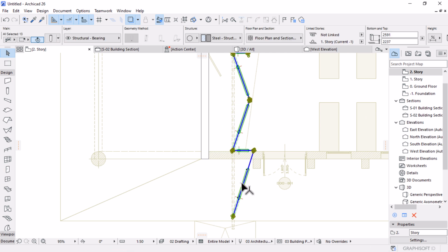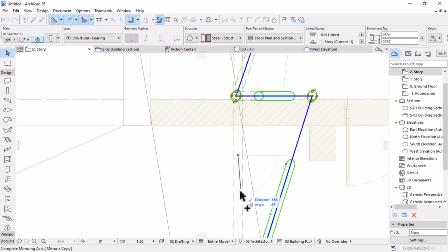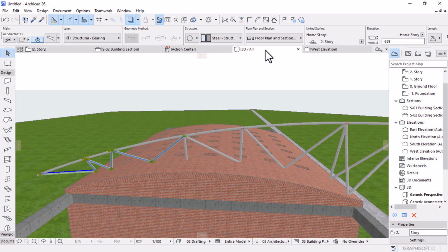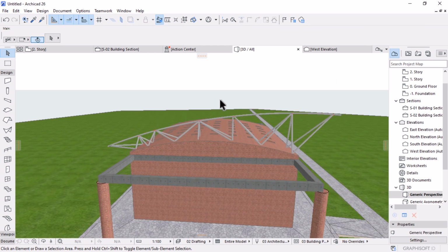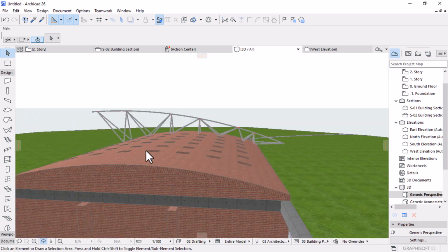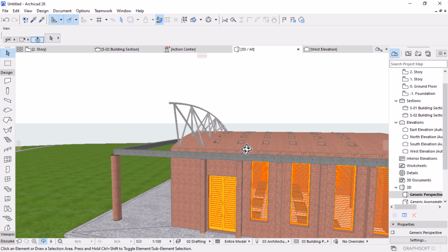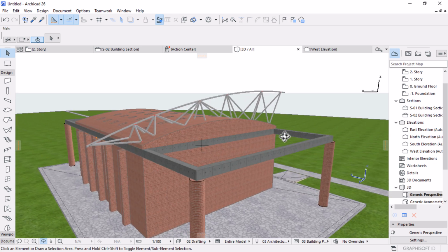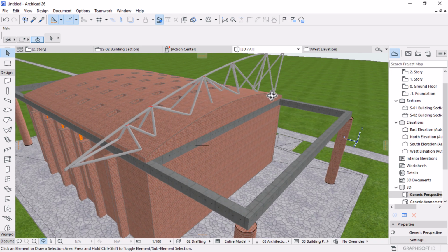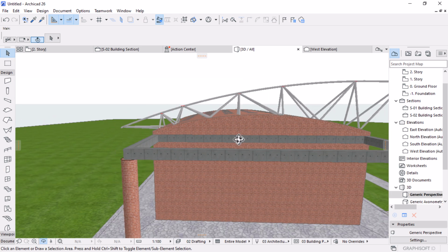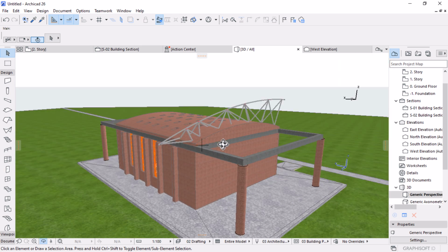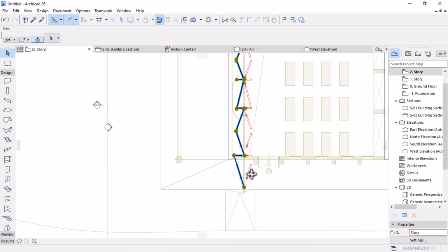Okay, so Control Shift M, use the midpoint of your beam so that you can have something like that. If you check on 3D, that's basically what you have. That's your truss. Obviously here is going to be a different truss, guys, because we don't have this splay or this bend, so it's going to be straight, and I don't think this one will be much of a problem.